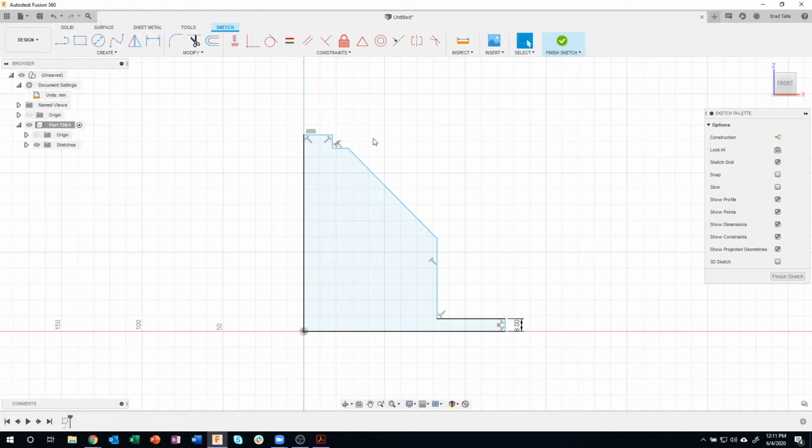Now, what I'm trying to explain is that previously, if you don't have that turned on, you might throw a dimension on, for example, this line right here, and it would do something like this. As soon as I typed in the height of that line, I get a really weird result. So by doing that auto scale at first dimension, it keeps my profile looking the way it should, but it just scaled it up a little bit. Okay. So again, using my drawing, let's just do maybe this top line to the bottom. That looks like that's supposed to be, my eyesight is really bad, 116.